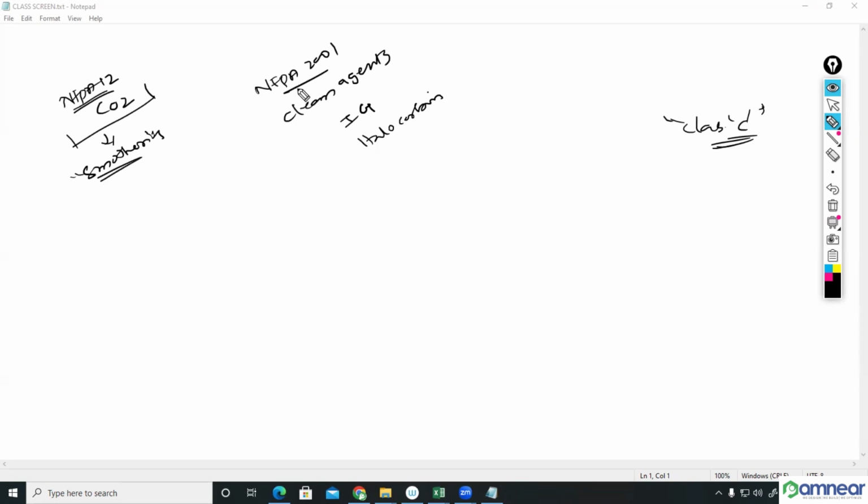With NFPA 2001, we have clean agents. Clean agents are halocarbons and inert gases. Inert gases means argon, krypton, helium; those you can use. Halocarbons come in different types. The most common type that we use is FM200, Factory Mutual 200, HFC-227ea, which is the code name of FM200. This is also a gas, but its extinguishing method is different compared to carbon dioxide. Carbon dioxide is not possible wherever people are present, in occupied regions, because once the carbon dioxide has fully filled the space, the oxygen concentration will decrease.